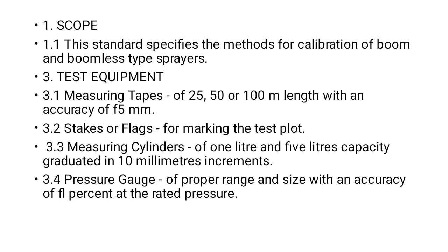Now in test equipment we require a measuring tape of 20 or 50 meter length with an accuracy of plus or minus 5 mm, stakes or flags for marking the test plot, and measuring cylinders of 1 liter and 5 liter capacity graduated in 10 milliliter increments. We also require a pressure gauge of proper range and size with an accuracy of 1% at the rated pressure.